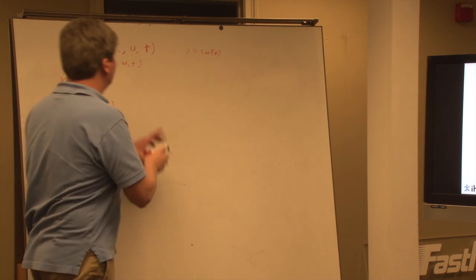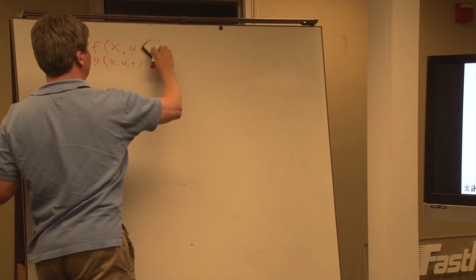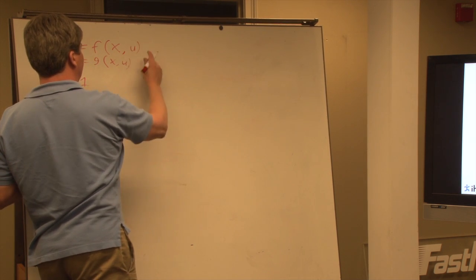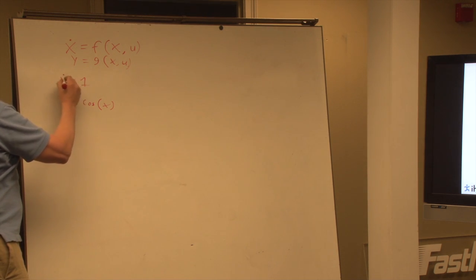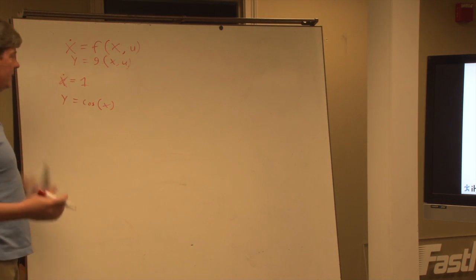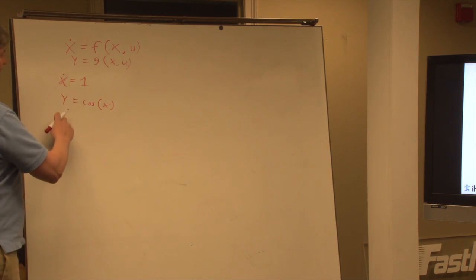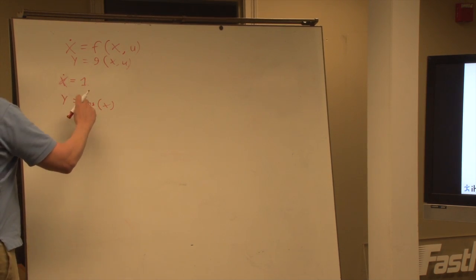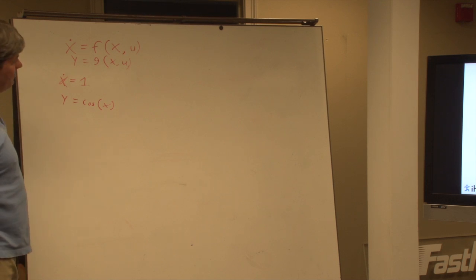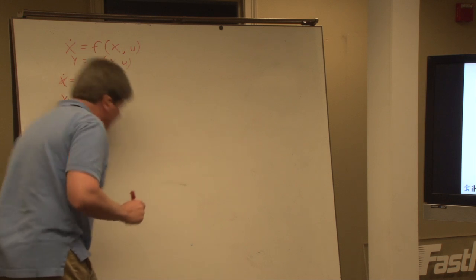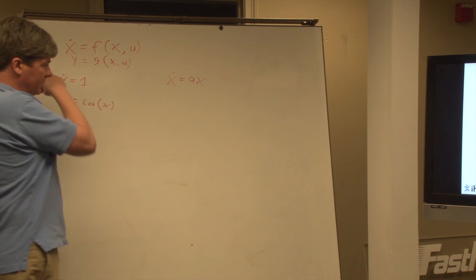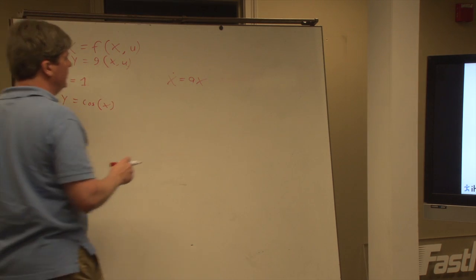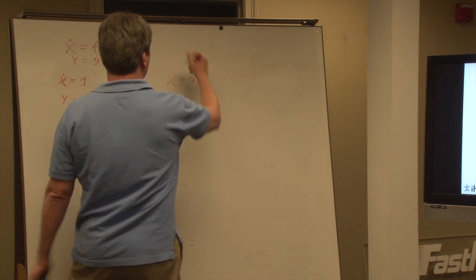But let's say you don't have a timer and we want everything to be a function. Don't put t in there. Then you just do the trick, where if you need to create t, you just have one of your state vectors essentially be t, like by just saying x dot equals 1, right? So as you integrate that up, you get time. So you can have an oscillator with a 1 degree of freedom system as long as you have nonlinearities in it. If you have a linear system, then you need 2, right? Because any linear system, if you just have x dot equals ax, all that can do is either blow up or decay to 0. In order to oscillate, you need something that looks like a mass spring damper.